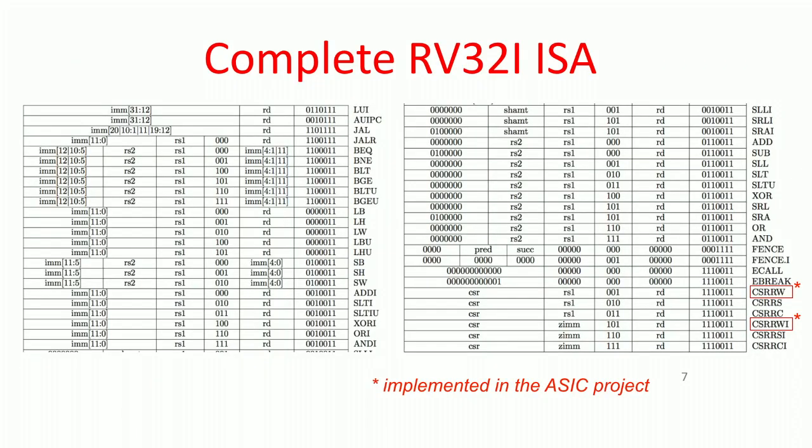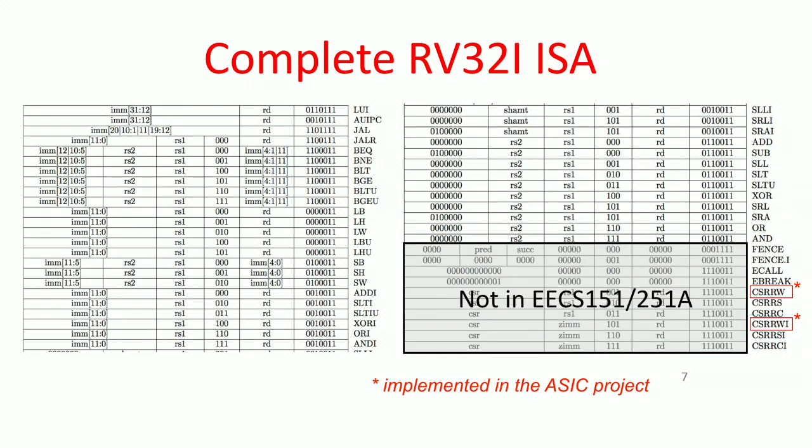And for the RISC-V, it's a relatively compact set. Here's a complete specification for this particular RISC-V. And we have all the instructions representative of all those classes that I talked about a second ago. And we'll be going through some of these in detail. Not all of them, the ones that are typical. In your project in the lab, you'll have to implement all the instructions. So you can use the same kind of formula that we're going to talk about today to implement an instruction, and you can generalize it to other similar instructions.